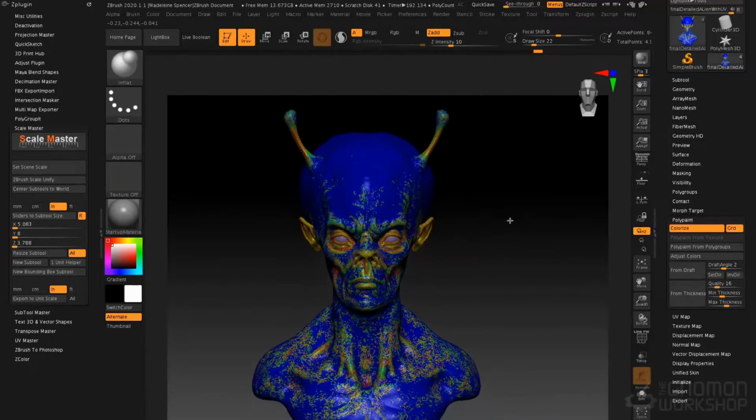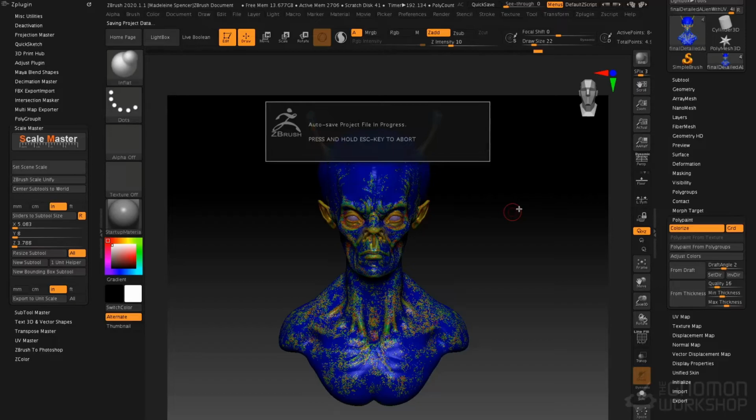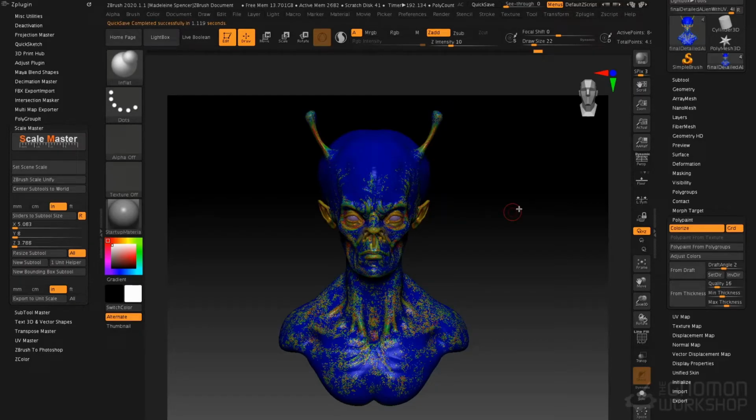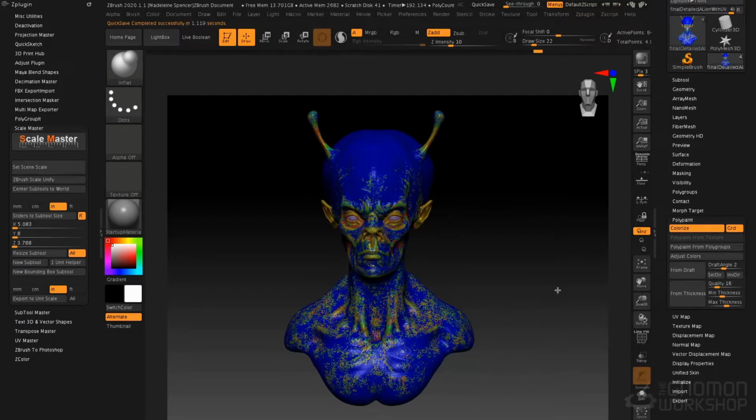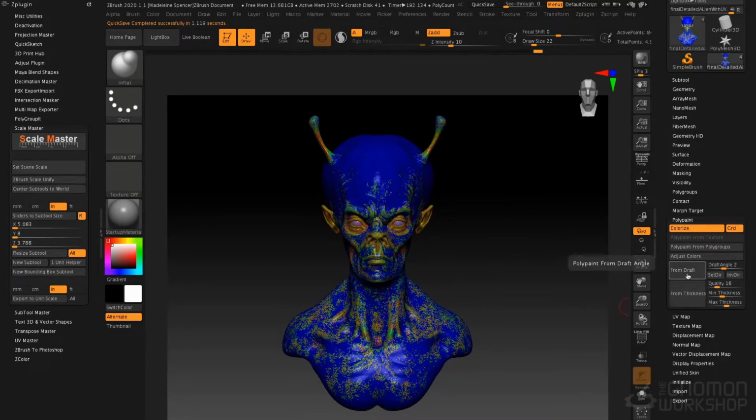So when we're trying to create, for example, an object that's going to maybe be injection molded with plastic, that's a solid object in a solid mold, we want to be very careful with our draft angles and our pull direction. So just like with from thickness, I'm going to orient the mesh on screen and then click from draft, and it will once again process and then give us a color-coded map showing us the draft angles. So let's do that now. Let's click from draft, and I will pause the video while it processes this and then return once it's back.